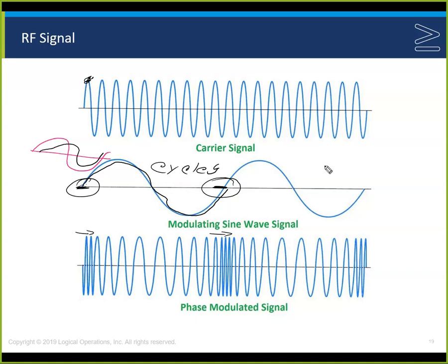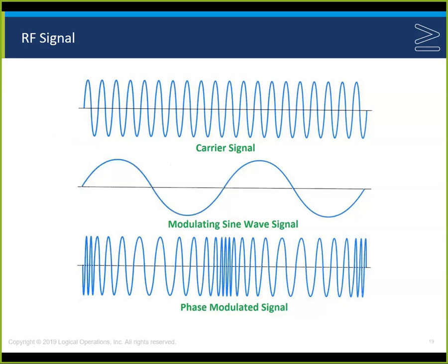That's where you get the noise. If we had a frequency or a phase modulation, we get this. They truncate the signal, chop it off, because we're not worried about how high it goes. We're just worried about the changes per second, the compression and spreading out of the signal itself. So the noise can actually be chopped off. That's what makes it so that you can hear FM radio.